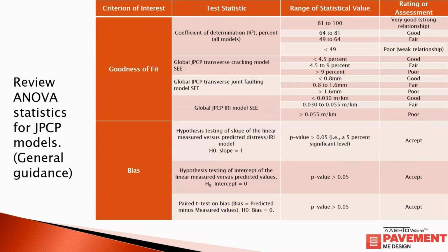And then on the concrete side, again, you have basically the same recommendations for R-squared, and then different ranges for the transverse cracking, joint faulting, and IRI models, and the same criteria for the hypothesis testing of the three: slope, intercept, and difference between predicted and measured data.